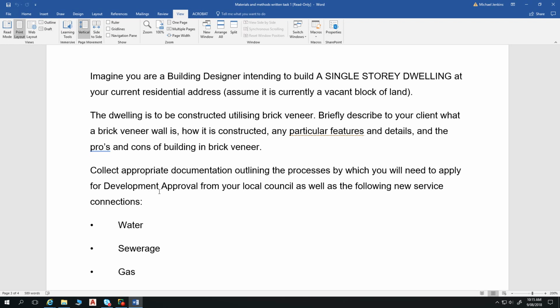And by the time you've finished studying, you should note this detail very well. So typically within our raft slab, we have some steel as well. So we're cutting through those steel rods. And then we have ligatures joining those together. This piece here is our concrete. And for those of you not so familiar with drafting, that's a break line. It's a very rough break line. There's more going on, but we're looking at this bit.